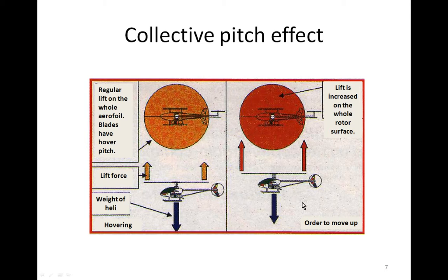Then the swash plate moves up. Blade pitch increases, so lift increases too, and we can see that the lift increases on the whole rotor area uniformly. Then the helicopter moves up, remaining in horizontal position.